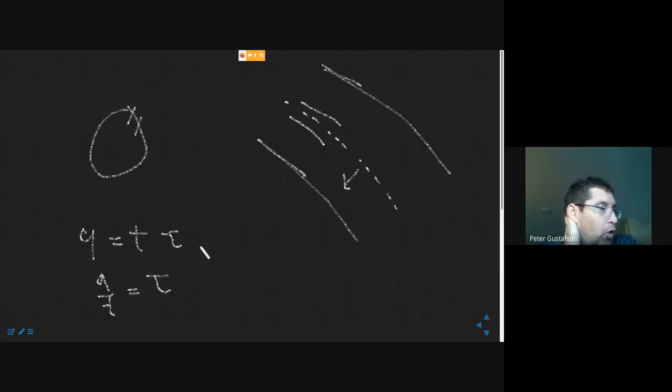All right, so Nicole asks another question. But even though the direction changes, since Q is a magnitude, we can take it out of the integral. Not quite. It's not because Q is a magnitude. It's rather because Q is a constant magnitude. Because it's a constant, it can come outside of the integral. And when I say constant, it's constant for this closed cell, right? We're going to amend that statement slightly later, but for now, that's the interpretation. It's constant within any given cell.